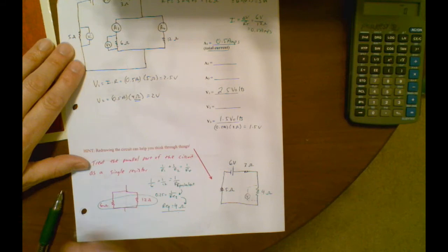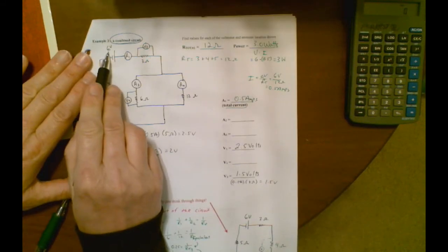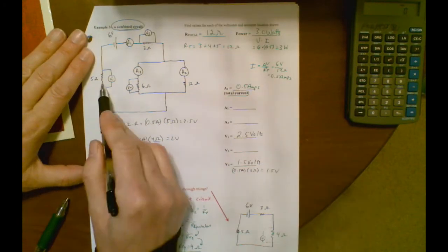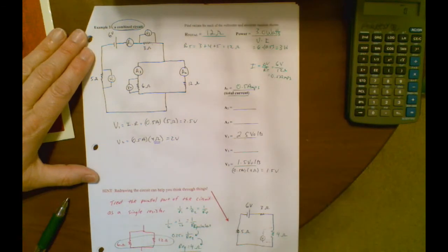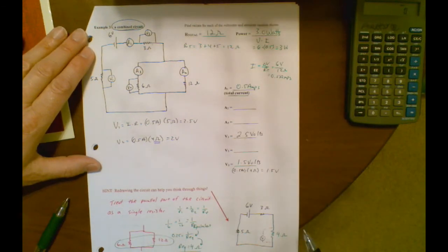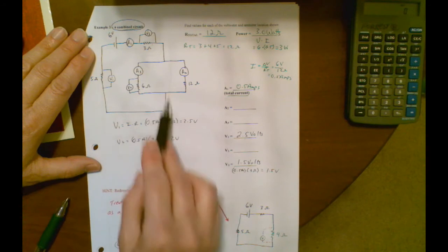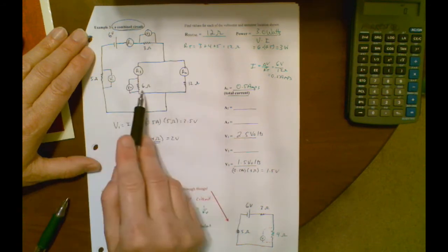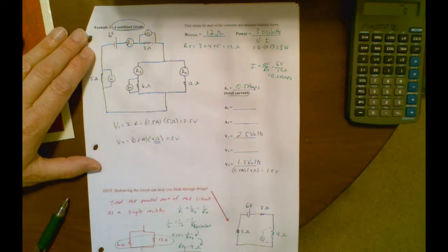The other way I could do this is I could note that the whole voltage of this circuit is 6 volts. And so I've used up 2.5 across here, I've used up 1.5 across here, that's a total of 4 volts used, which means since I've got to use the entire voltage up, no matter which path in the circuit I take, the voltage across this resistor would be 2 volts, and the voltage across this resistor would be 2 volts.